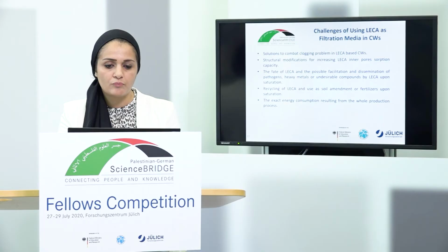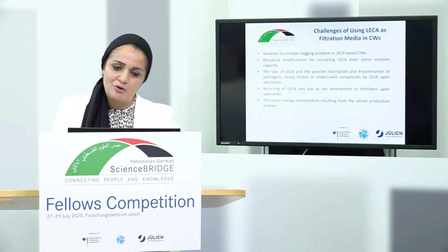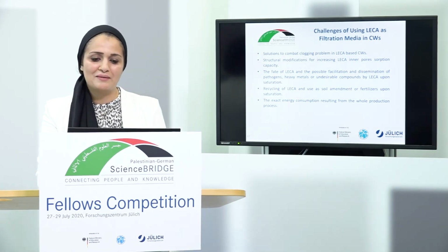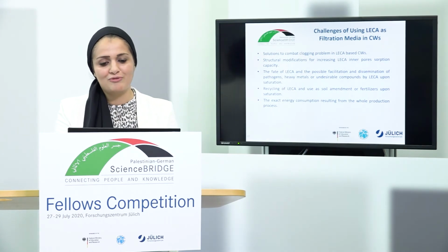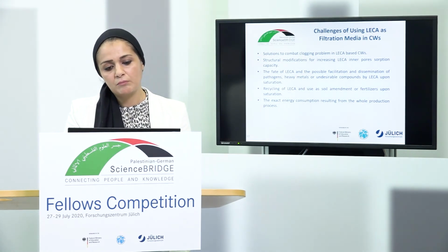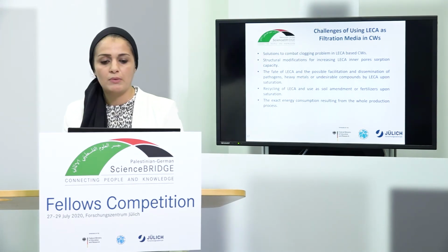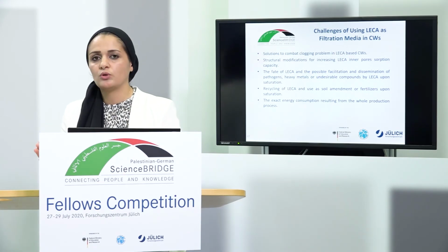But there are challenges in using LECA, of course, a negative part to all of this. In constructed wetlands, there is the so-called clogging problem, where at a certain point this material is saturated and cannot be effective anymore, so it needs to be regenerated.